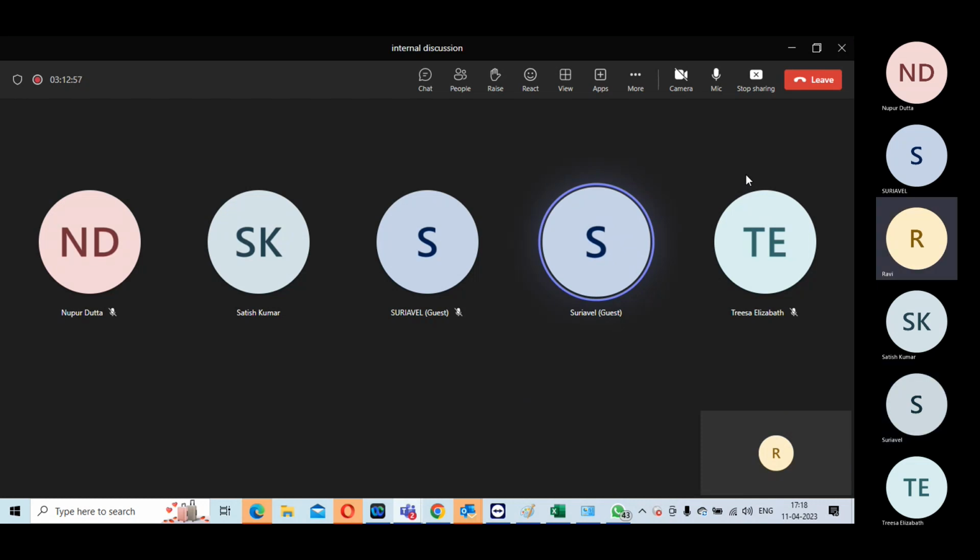If it is a sharp edge, it will create crosstalk to the other clock. The crosstalk effects will still be valid if you are treating it as asynchronous, so this clock edge will move because of the crosstalk. If you have set it as a false path, the noise is ignored. I think now the software could have taken care of it, but keep this in mind.